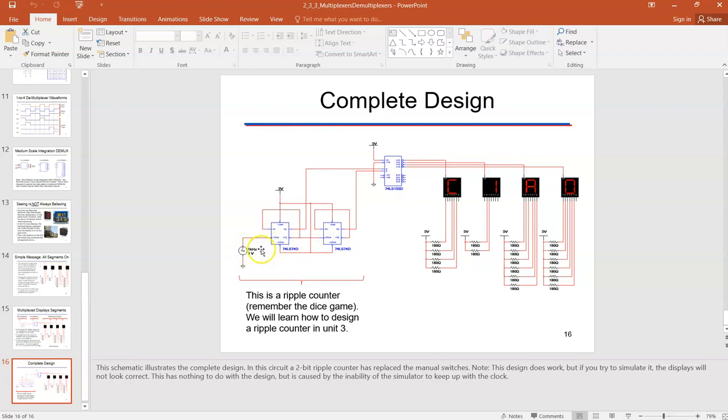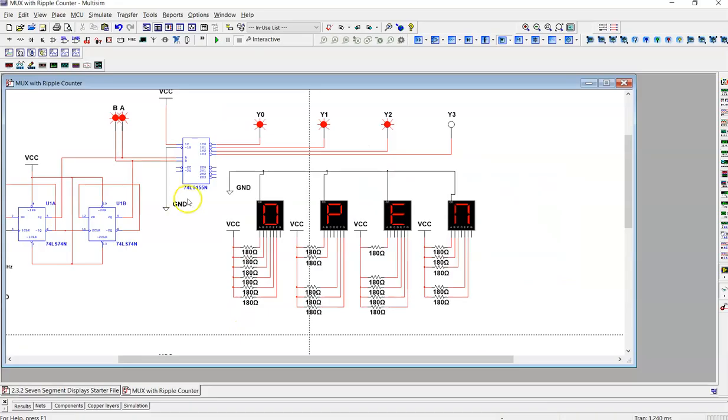And so you don't have to toggle automatically with the switch, because we could put a switch here and toggle it at our own frequency. You can put this clock signal, and you can adjust the frequency, which is the hertz, to have it do it for you automatically. And what you're going to see is these are going to turn one on, the other 3 off, the next one turns on, the one that was just on will turn back off. So this is the design in the end that you're shooting for.